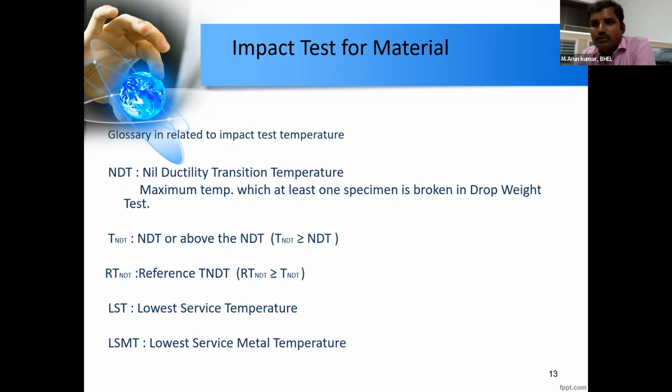But for the maximum soaking time, or if a power cut happens during soaking or during the cooling cycle, guidance is not provided in our ASME code, and much literature is also not available. If it is in the heating cycle, the heat treatment will simply be continued once again.